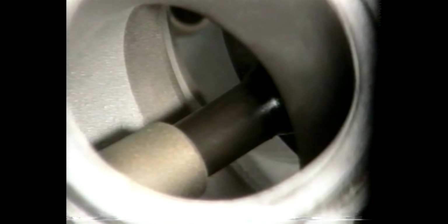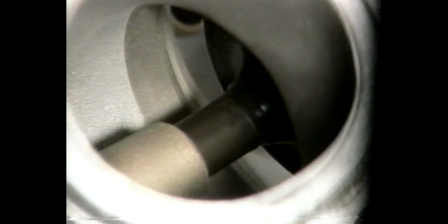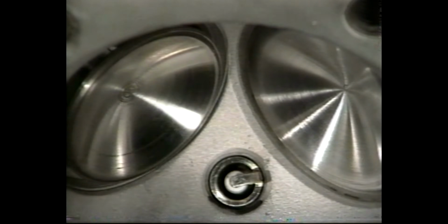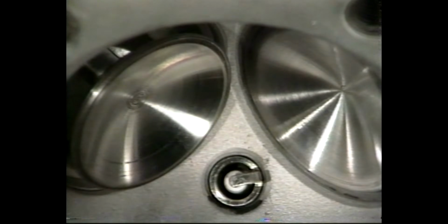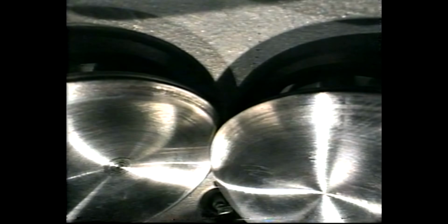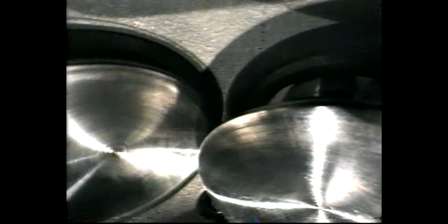Secondly, the design of the head also strongly controls the flow of the fuel-air mixture into the cylinders. Therefore, it is absolutely essential that the flow capabilities of our heads match the physical requirements of our motor. Both the valve-to-valve clearance and the valve-to-piston clearance specified by the manufacturer must be strictly observed, so that valves and pistons do not collide and destroy one another during motor operation.